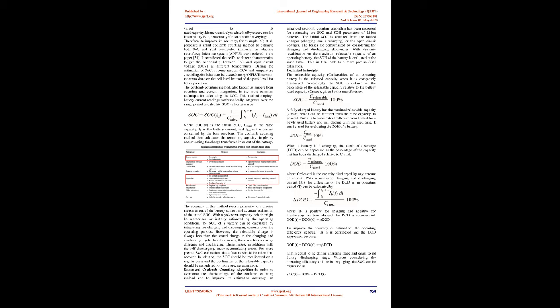State of charge, SOC, is a relative measure of the amount of energy stored in a battery, defined as the ratio between the amount of charge extractable from the cell at a specific point in time and the total capacity. Accurate state of charge estimation is important because battery management systems, BMSs, use the SOC estimate to inform the user of the expected usage until the next recharge, keep the battery within the safe operating window, implement control strategies, and ultimately improve battery life.